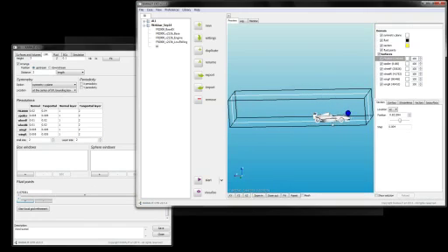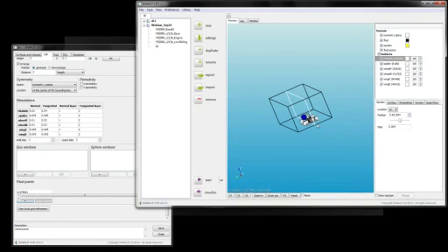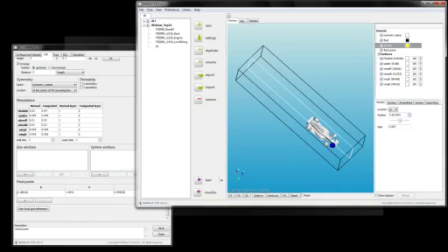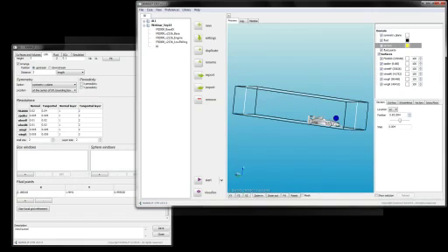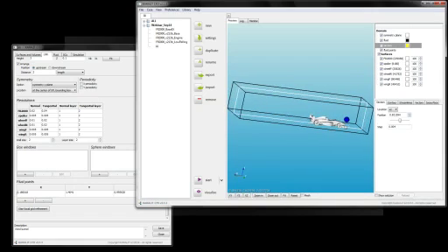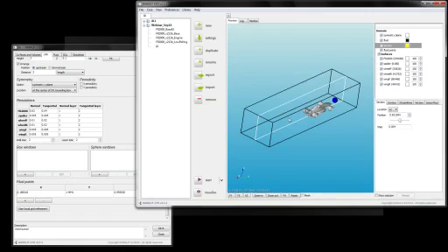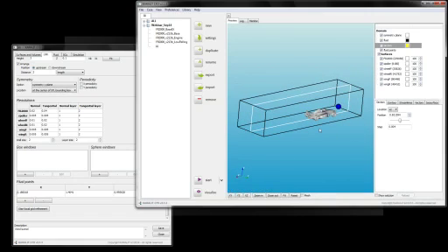It's just a point. It needs to be somewhere in the fluid domain that I'm going to use, so that the grid generator knows that it needs to keep the cells in those areas. Because if, for example, the inside of the car was of interest, I would need to put the fluid point in that area. And also, if the inside and outside were connected through some heat transfer, for example, you would add another fluid point to the inside as well.